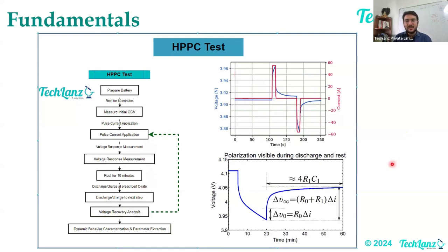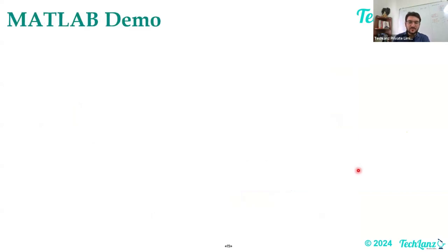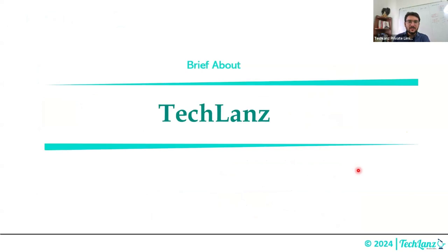At the end, what you want to get, what Lokesh also mentioned, after this analysis, you have to fit the curves to get R1, C1 and R2, C2, which is important from this perspective. Whatever Lokesh showed you, he rightly inputted in the simulation tool. You have to extract that from the cell testing. So cell testing also becomes very important when you have to understand the battery modeling approaches. I think this is already done.